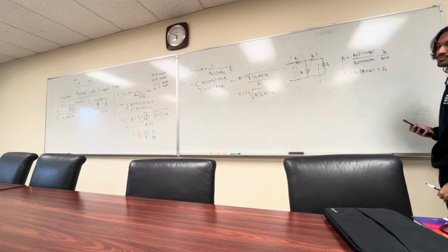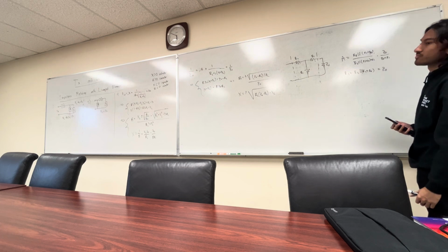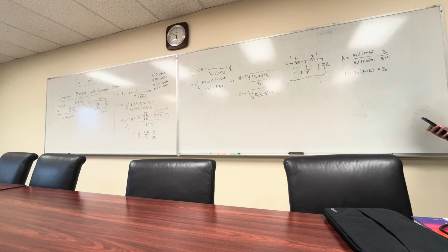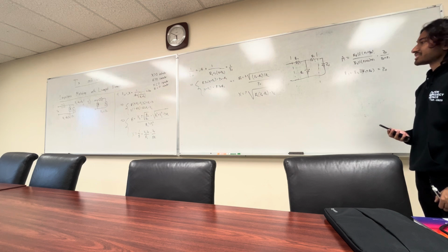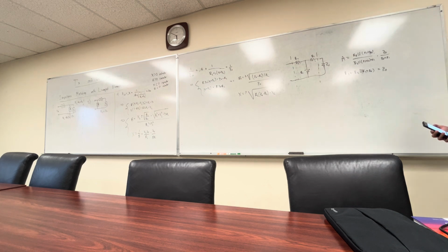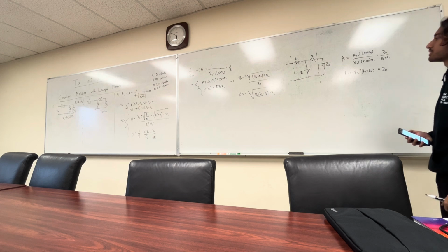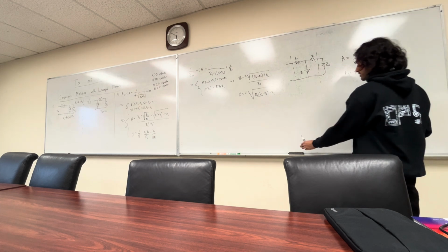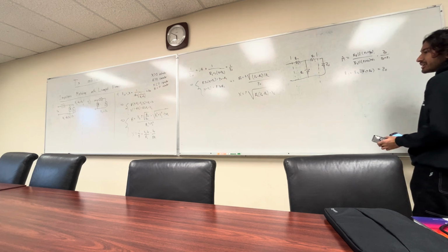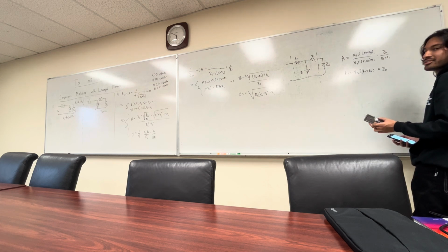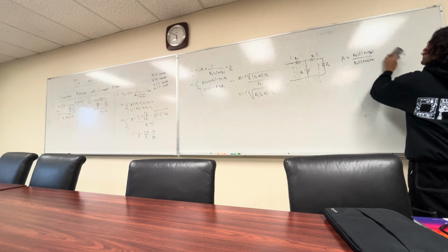Is there a reason why we're using T-pad attenuators instead of pi attenuators? It doesn't really matter. I think the math is a bit more digestible for a T-pad attenuator, and I think pi attenuators can give you a bit more attenuation. I could be wrong, but for all intents and purposes, it's practically the same. I think the calculator also has a section for pi that could generate both T and pi. You can compare and contrast the two.